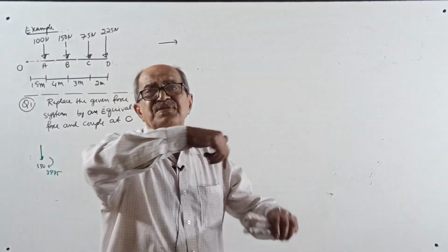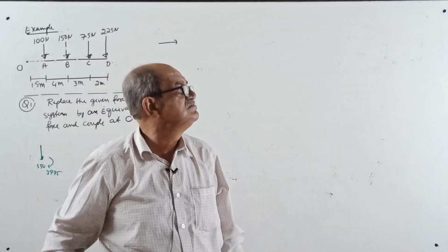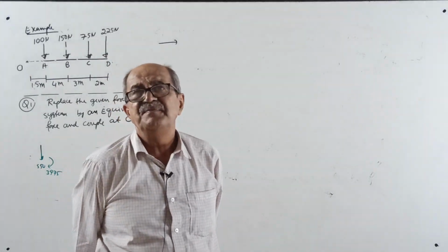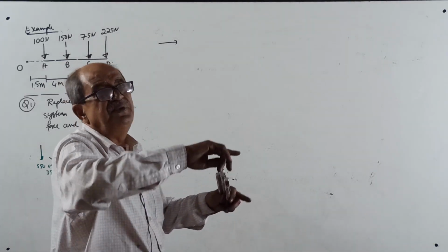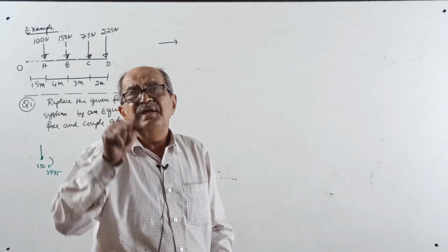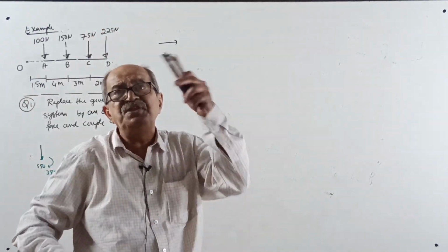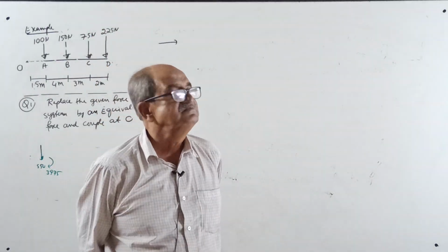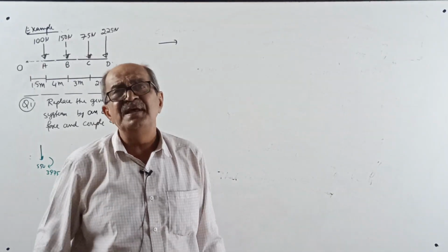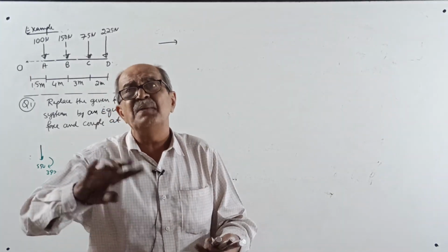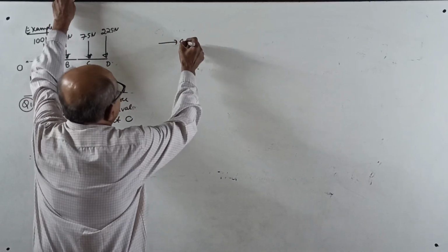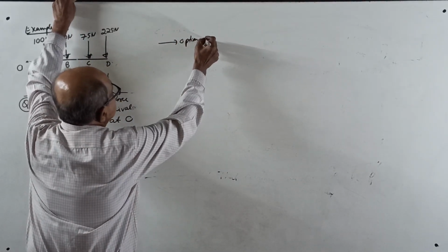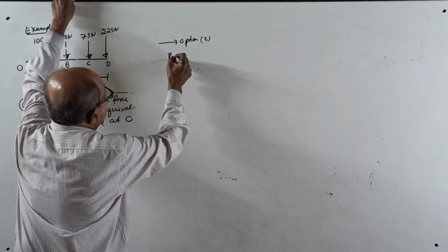That itself is, you shift it to the required point. Then find the algebraic sum of moments of the entire force system about that point to which you have to shift. That algebraic sum of moments itself is the couple. That's all. Okay, start now. Now option B, see how fast it is. Option 2, resultant force.